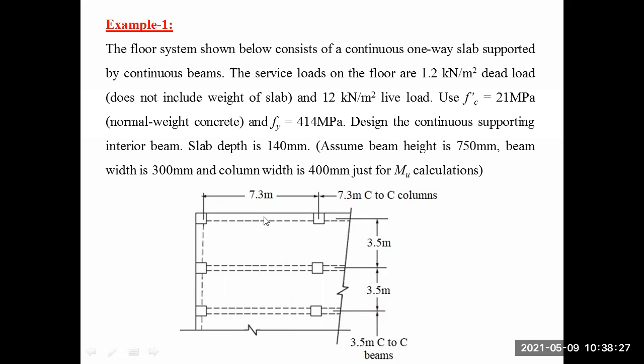The slab is giving its loads to this side and this side. The shortest side would transfer the load of the slab to the beams. Because this side is the long side, even if it is supported at this end with columns, you see, we don't have a beam over here. It's not shown. No, there is no beam. So the beam is continuous in only one direction.